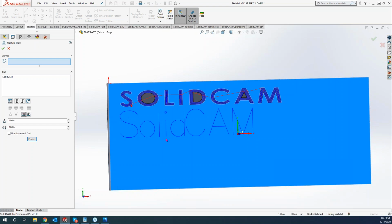And like I said, this is a great single line font that works really well, like using a spot drill or actually a specific engraving tool. If you guys are doing a lot of engraving, I would definitely recommend going out and buying a dedicated engraving tool for that. But you guys can use whatever tool you like. We have a lot of customers that are using ball end mills in there that really leave a good finish that way too. And what I'm going to do now is just space out my lettering so it's not so packed in there.